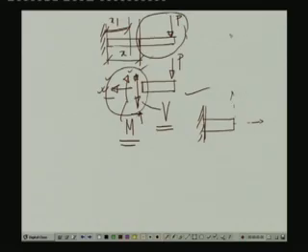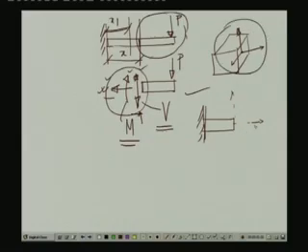If you remember the coordinate axis system as we discussed earlier when we evaluated the stresses. This is the positive x direction along which we have taken normal stress, this is the positive y direction, and we had taken this as positive z direction. To match with this criteria, our axial force on this particular section is positive, the shearing force is positive over here, and the anticlockwise moment, the perpendicular to which is projecting out of the plane, we call positive.